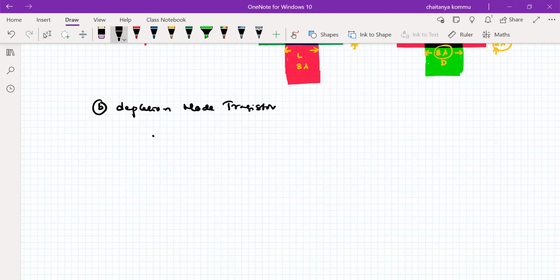Okay, the diffusion is something like this, and polysilicon is something like this. Usually it is 4:1. Okay, 4:1 dimensions that we have to consider. That means if the dimensions of the enhancement type transistor is 1 unit, the depletion type must be 4 units. It should be okay.